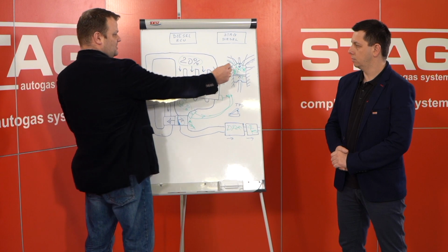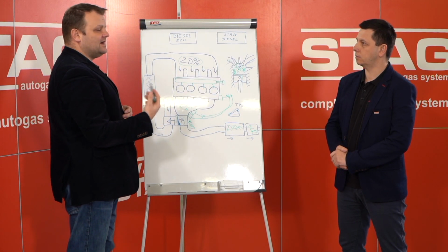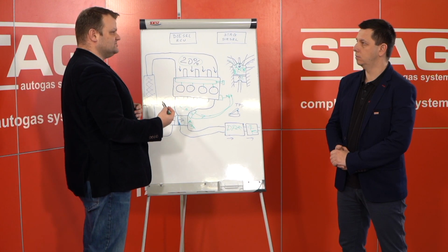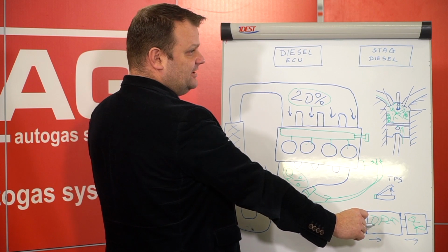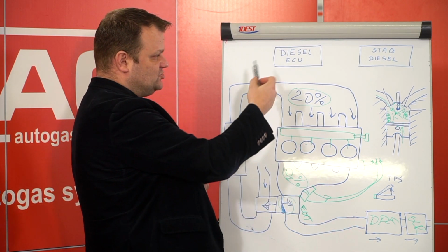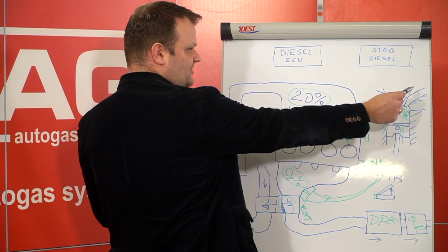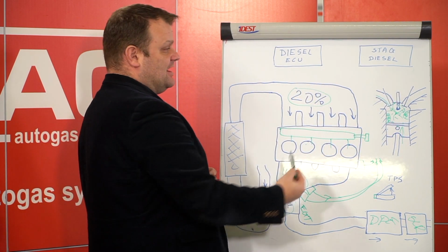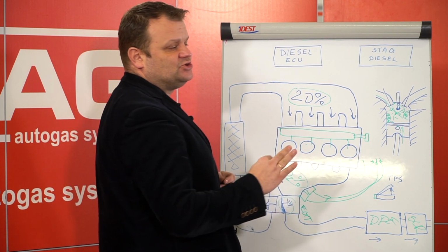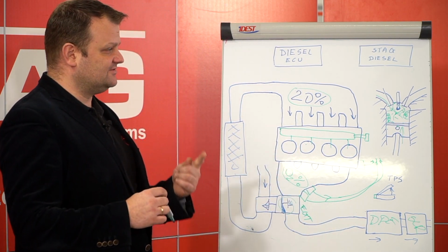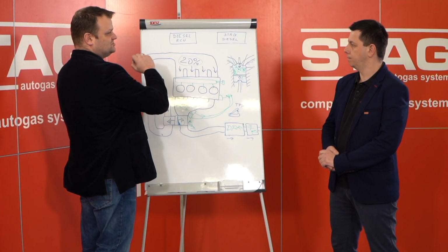Of course, the exhaust valve, because when adding the gas, during DPF cleaning the diesel ECU strategy is raising the diesel dosage, or it's spraying additional fuel on the exhaust valve, and is raising the temperature of the exhaust gases. That's why we need to control it to be sure about efficiency and thermal protection.